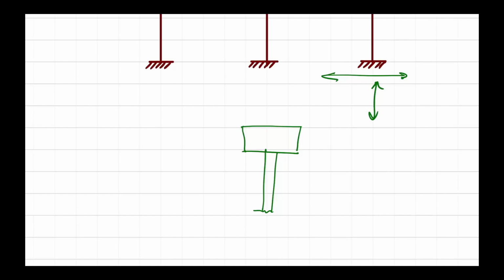But my main idea is that the pile is generally slender. The cross-section, because of the load carrying mechanism that we expect, is for the axial load only. So if you want the axial load only, the cross-section of the pile can just handle that axial load, alright? But axial load is the stiff mode of the member, but bending mode is the weak one. And again, it's not designed for that. So if you have a foundation like F1, F1 means just one pile, like this in the picture, then the rotational rigidity is very, very small, very weak under rotation.